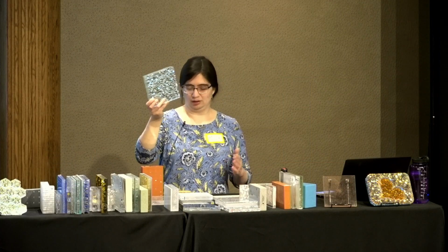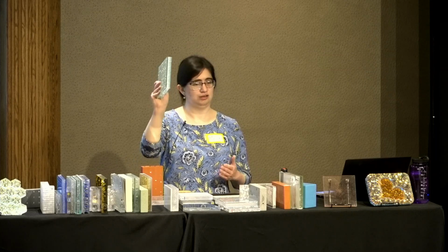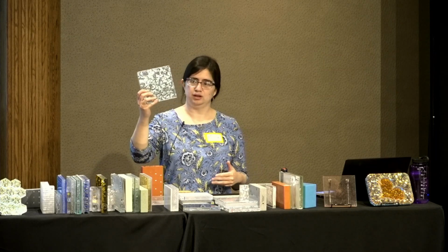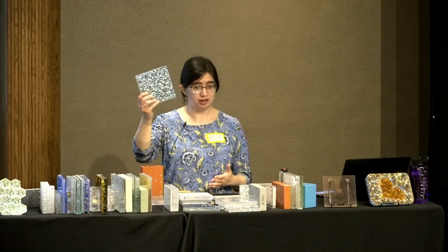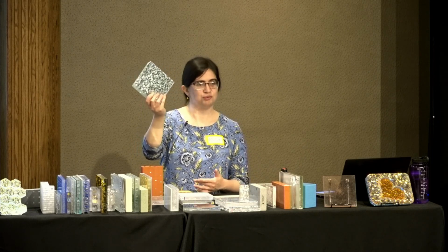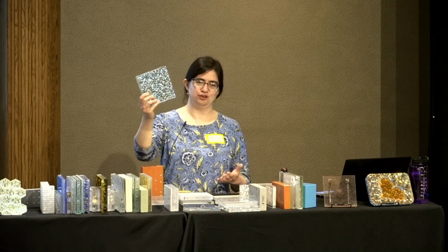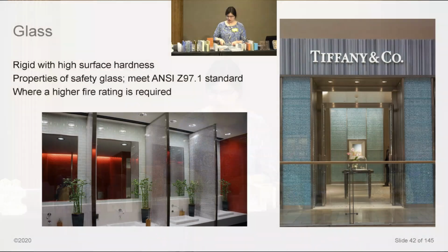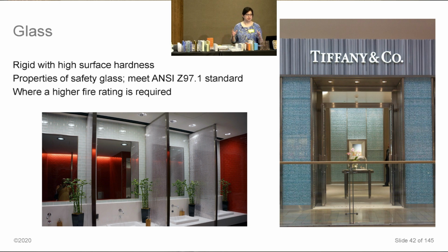The glass and the resin, but the glass in particular, is laminated together. It's made in layers, so it qualifies for safety glazing. It can be used for things like balustrades. You can stand on top of it if you want. So it's very rigid, extremely durable. There's also a couple more options in the glass for outdoor use. More of the mirrored glass can go outdoors than the resin. It is also all, again, UV stable, non-yellowing.